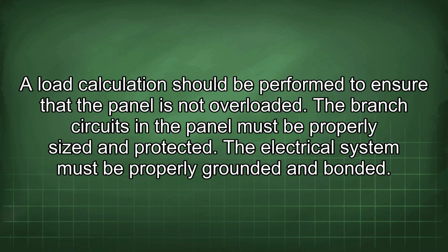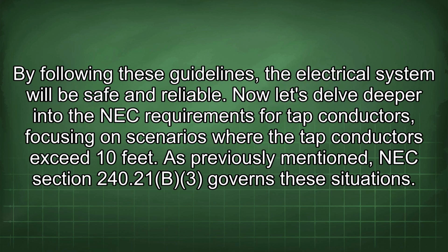A load calculation should be performed to ensure that the panel is not overloaded. The branch circuits in the panel must be properly sized and protected. The electrical system must be properly grounded and bonded. By following these guidelines, the electrical system will be safe and reliable.